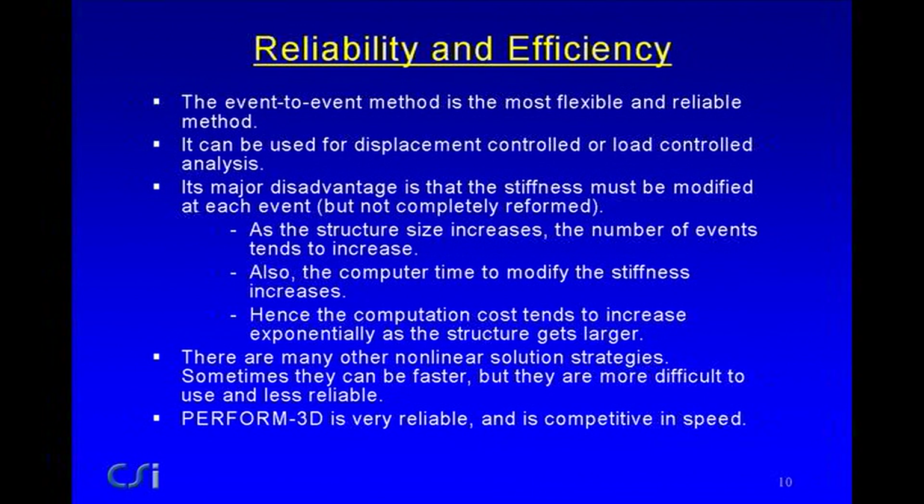It has a major disadvantage, that the stiffness must be modified at each event. Let me say that one way to modify the stiffness is to reform it completely. That is really rather expensive. Another way is just to recognize there are certain limited changes in the stiffness matrix, so just do a modification rather than a complete reformulation. That is a lot more efficient.